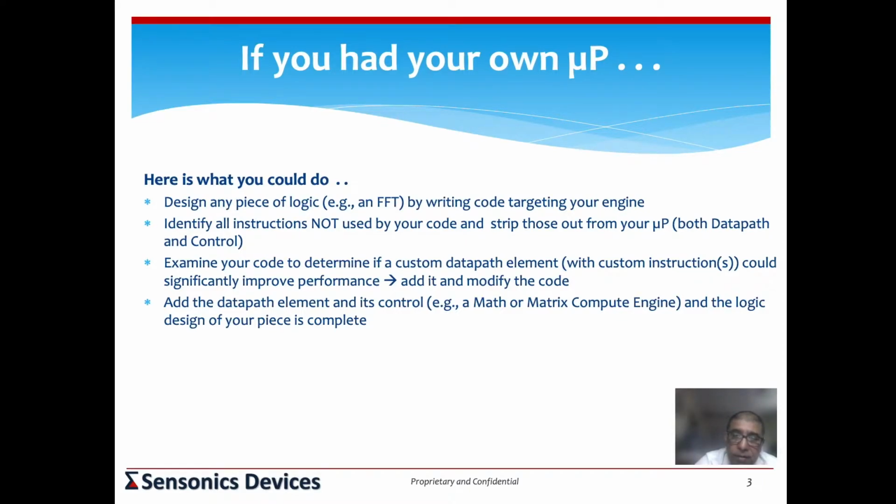But what would happen is that while you're writing that code, as I described, maybe for an FFT engine, you might want to add a little bit of additional logic to improve its efficiency. Maybe reverse binary addressing would be a little piece of logic you would put into the addressing logic, and you would enable that by some mechanism which you implement in your microprocessor, and the rest of it stays as before. Okay, so this is something that you could do.